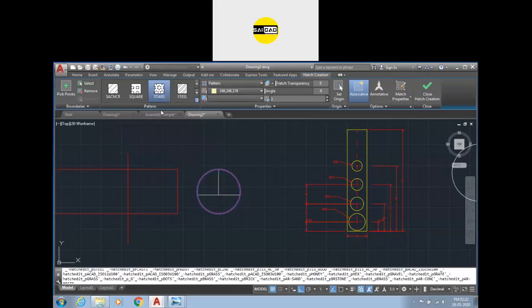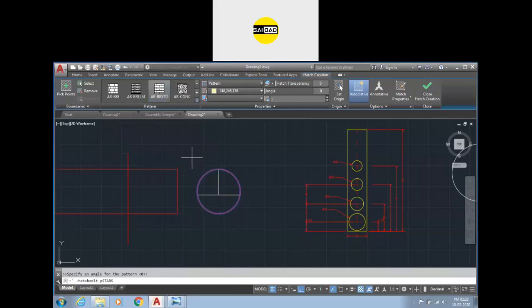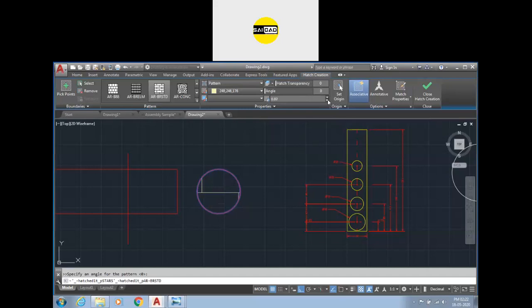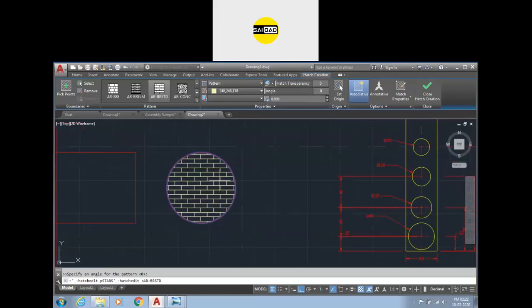So select any type you need, and after that you see that you cannot see the same shape we have here because the scale right now is higher. So to change the scale, here is the option, hatch pattern scale. So if you zoom out or decrease the scale, you can see that the hatch will be shown like that. If you want to increase, simply increase the scale like that.